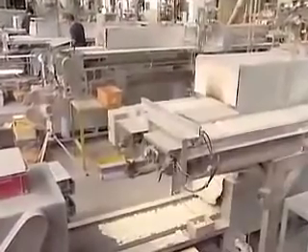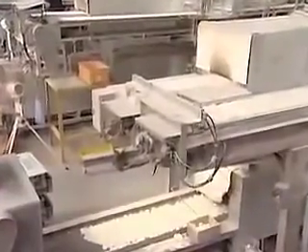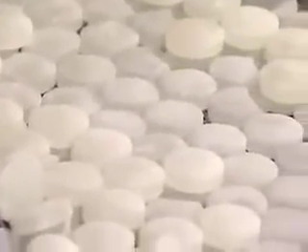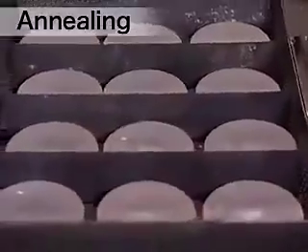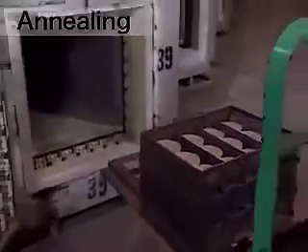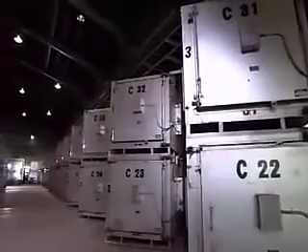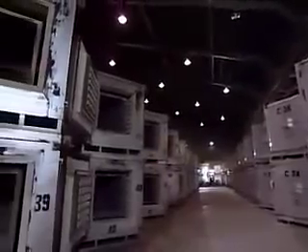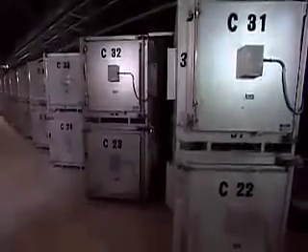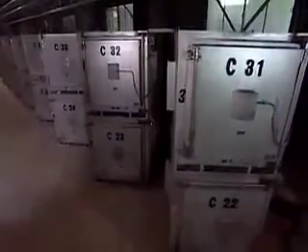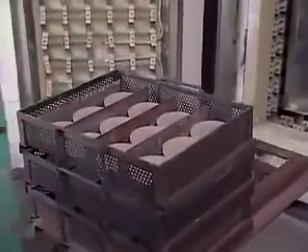After going through these processes, the glass materials take on the shape of a lens for the first time. Although having the shape of an almost completed lens, pressed glass at this stage has intense internal thermal stress. To remove this stress, pressed glass is subjected to a process called annealing. First, the pressed glass is heated to 500 degrees Celsius in an electric furnace and then gradually allowed to cool. It is during this process that the internal stress is relieved and the precise adjustments of the refractive index are carried out.